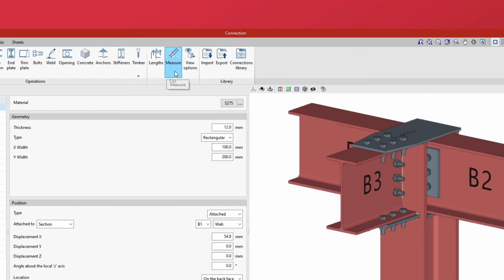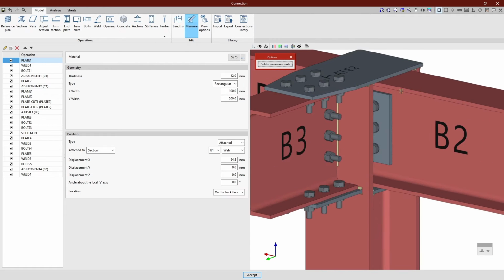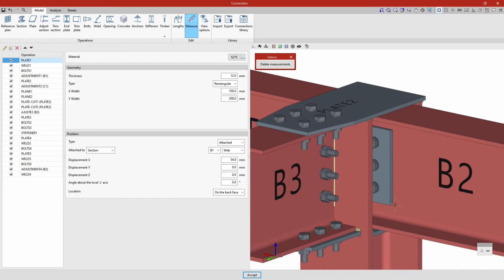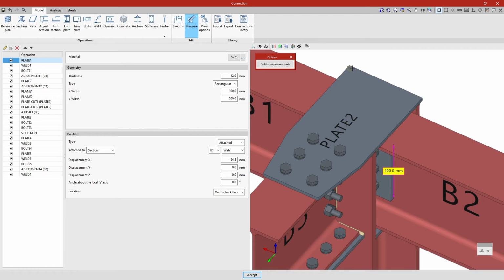The next option allows us to measure a distance between 2 points by selecting them with the left mouse button in the 3D view and thereby entering a measurement in the model. To enter more measurements, we simply continue left-clicking on other points. During this process, we can erase the last introduced point or erase all introduced points. To confirm the entered measurements, we right-click on them.